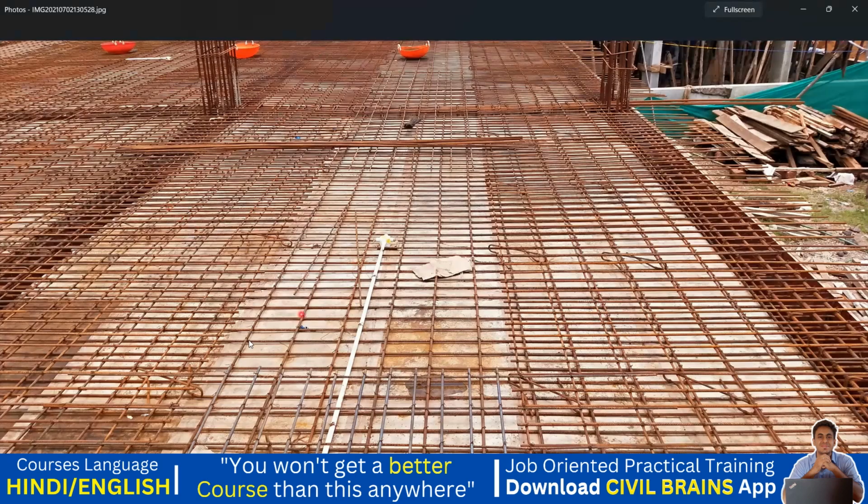What you can see, you can see the bottom steel here. You can see in the center portion in this way. In this way, this is your bottom steel which goes, and then this is your top extra steel. You can see from here, this is a top extra. From here also top extra. In the same way, in the other direction also, your steel will go in this direction. You can see similarly here also that direction of steel will go. Okay. So in this way, whatever was there in the drawing, the same has been executed practically on the site.